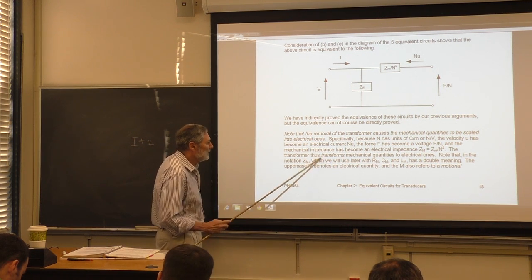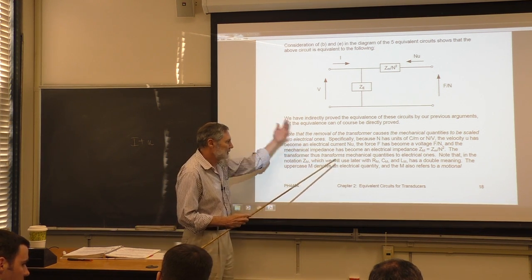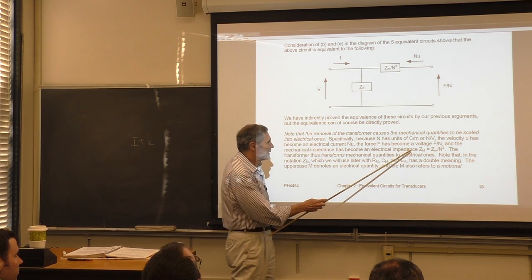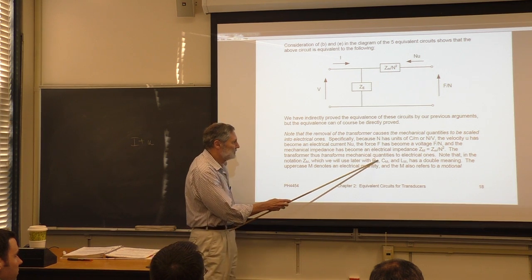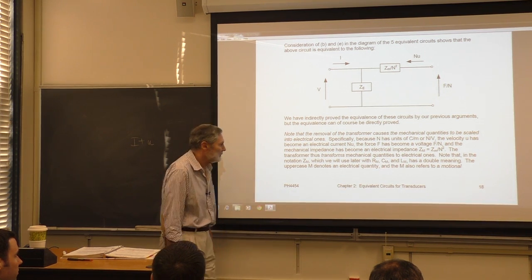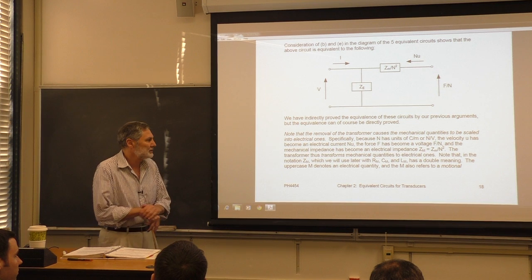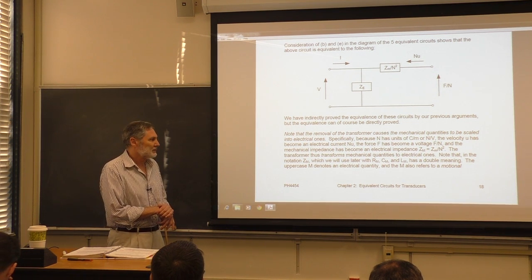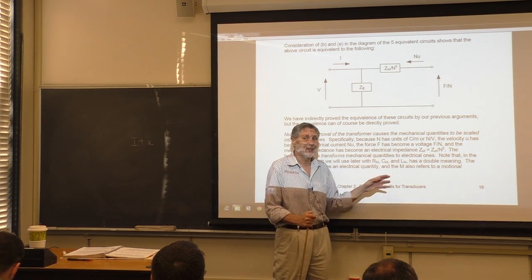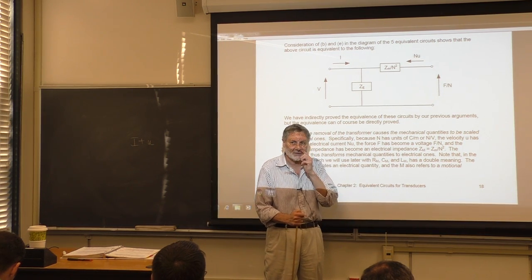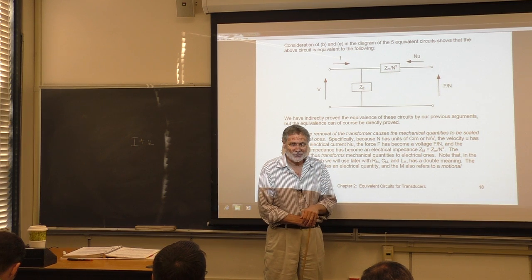And we'll continue to do this. In here can be involved resistance, capacitance, and inductance, and we just use these capital letters. We call those the motional resistance, the motional capacitance, and the motional inductance. And please remember, these are electrical quantities. They correspond to the mechanical quantities. That's why we have the word motional in there.